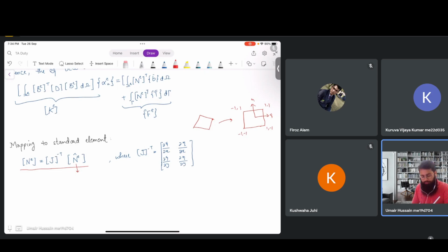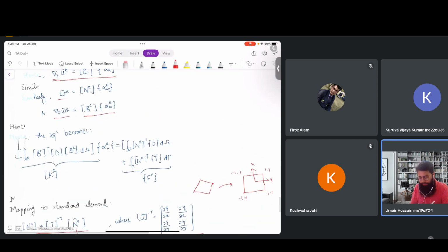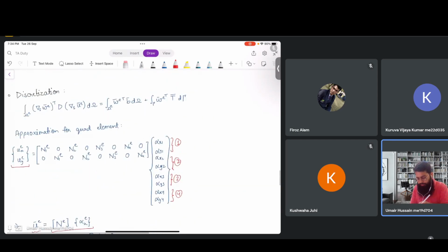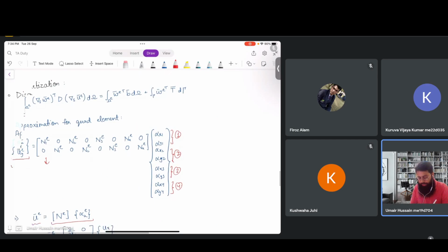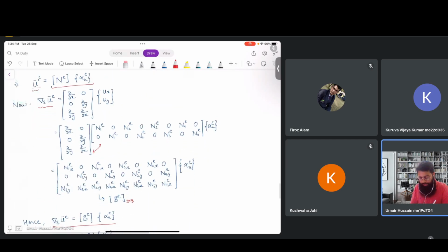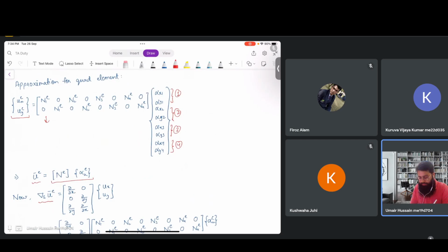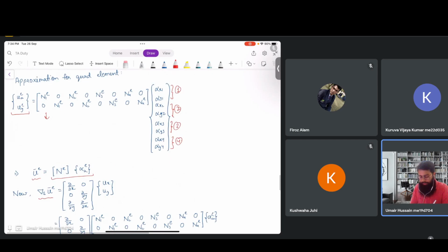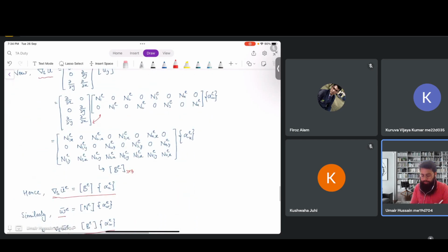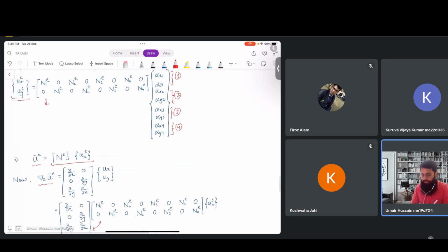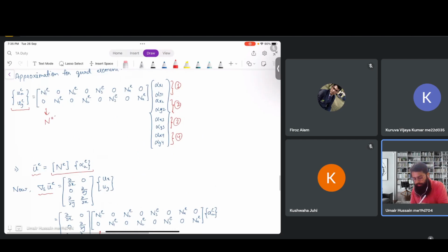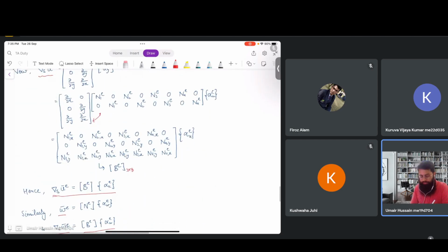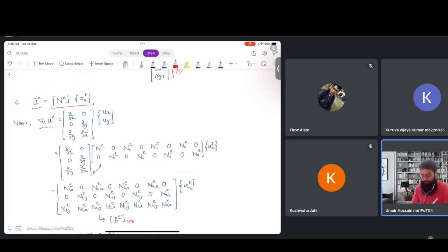The formula for this J inverse transpose is this, and this will give us the N matrix, right? This matrix over here. But how do we get the B? Once we get this, we just need to reshape the N matrix that we got into the B matrix. If you see this N matrix here and this B matrix here, N is just reshaped to get B, right?